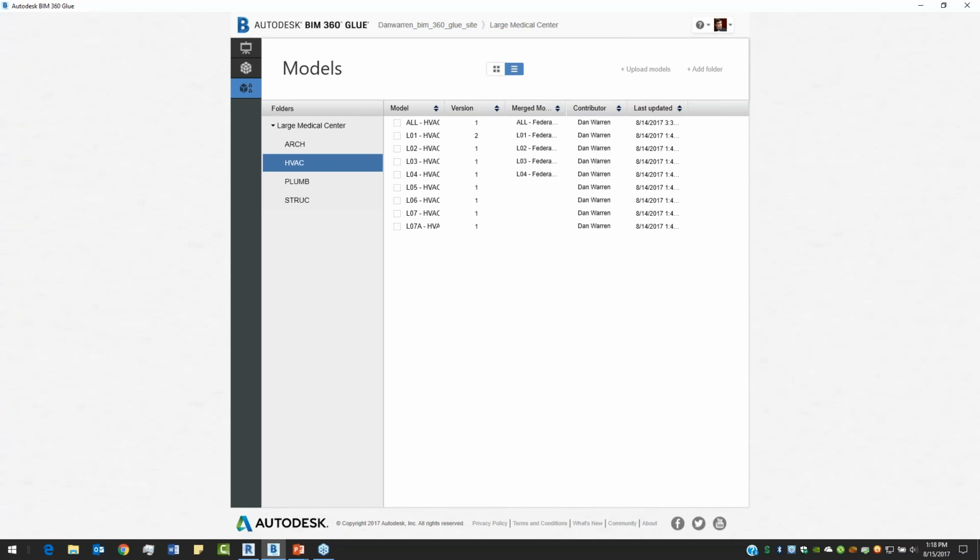And a lot of times I see that the coordination efforts tend to be structured very similar to the project documentation, unless it just gets too detailed and it has to be broken out. Now remember here, with any one of our models that we're uploading, it's easier to take a model that's already up there and break it into 2 smaller pieces than it is to try to bring together two smaller models, because it's going to really mess up your coordination and tracking efforts, right?